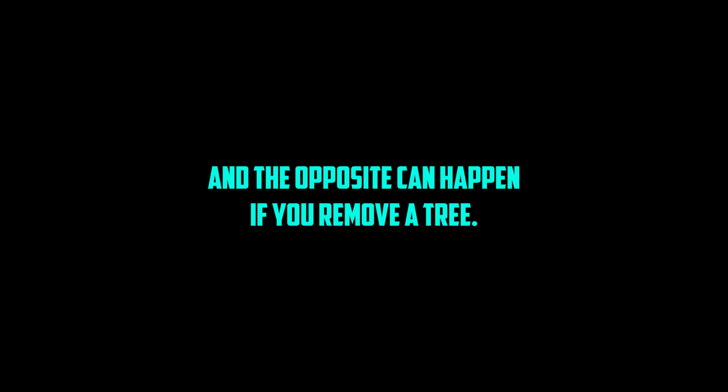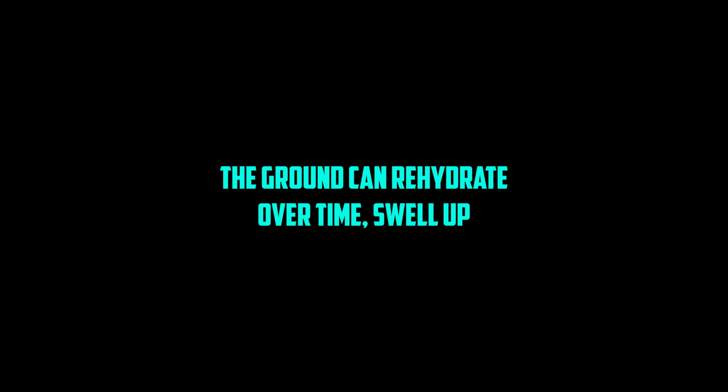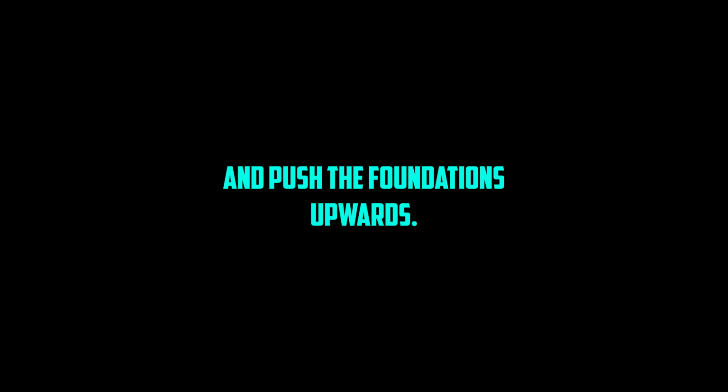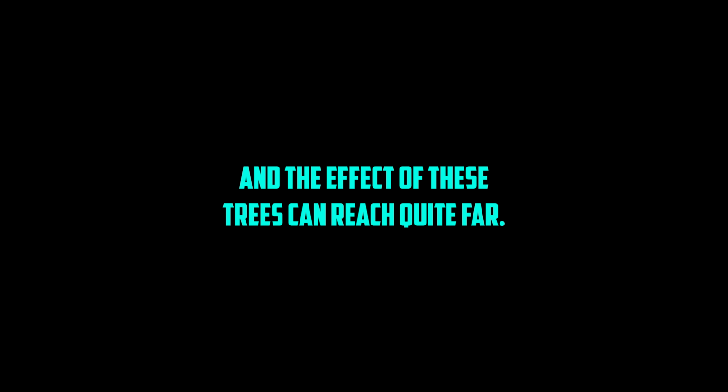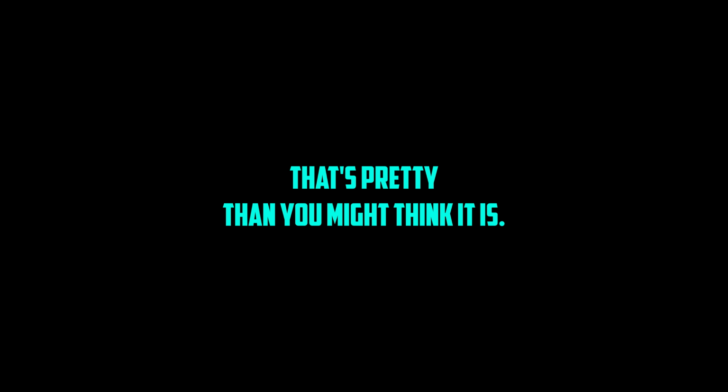And the opposite can happen if you remove a tree. Precisely. If you take out a big tree that was drying the soil, the ground can rehydrate over time, swell up, and push the foundations upwards. That's called heave. And the effect of these trees can reach quite far. The handbook mentions up to 30 meters. 30 meters, wow. That's further than you might think.